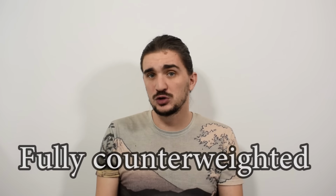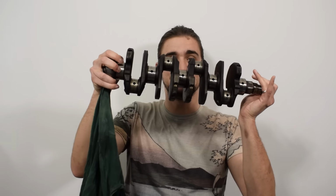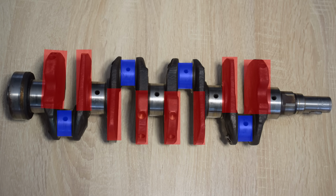And this is why often when a crankshaft is described, you're going to hear the term fully counterweighted. A fully counterweighted crank looks like this. A fully counterweighted crankshaft is going to have two counterweights opposed to each rod journal. An inline 4 crankshaft that isn't fully counterweighted is going to look sort of like this.